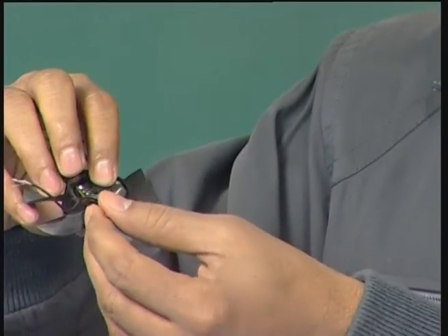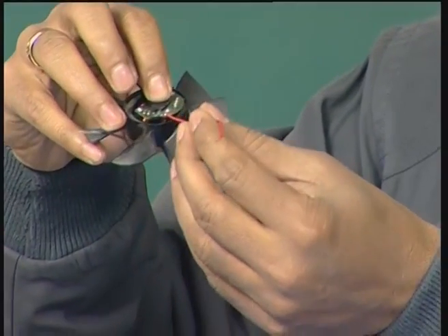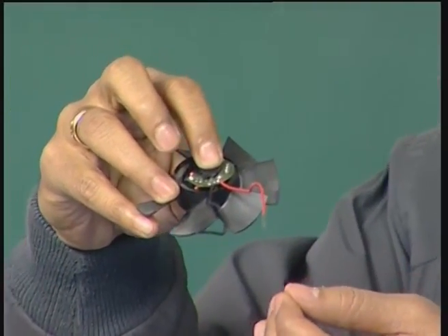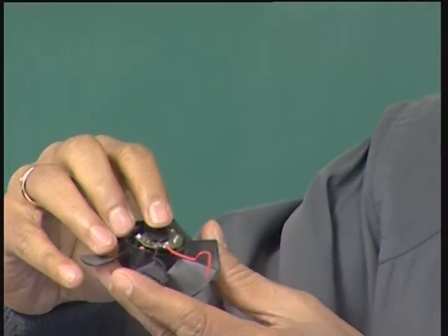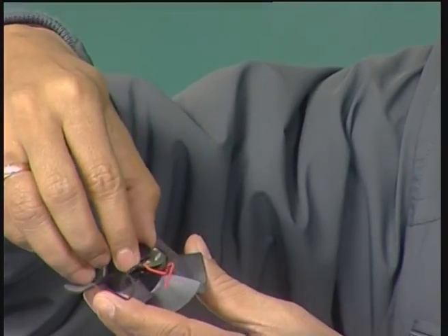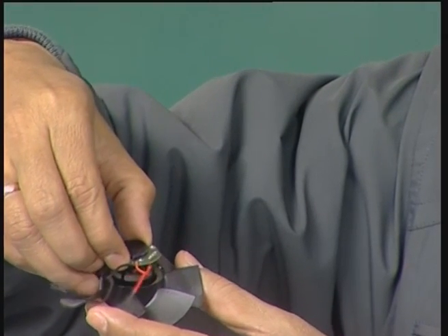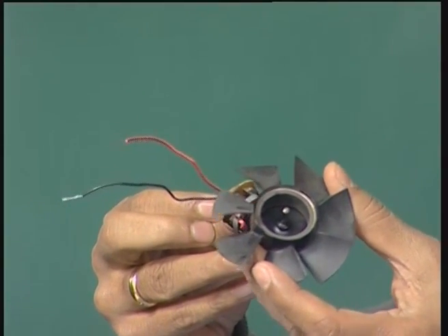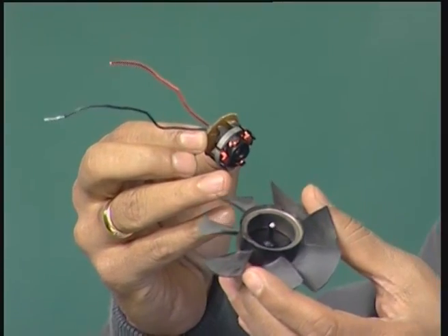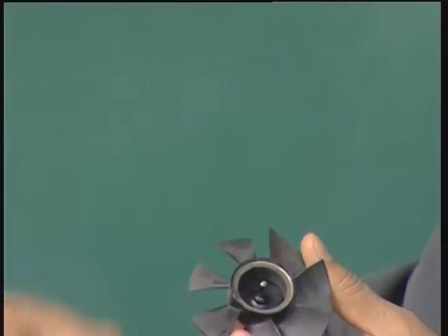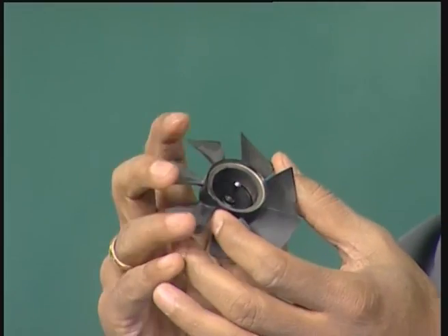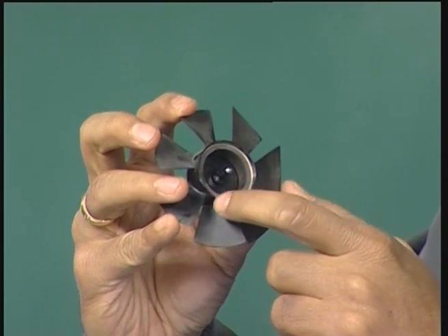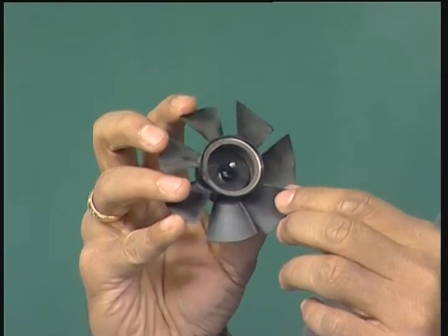These are basically the connectors for connecting the DC power supply, which is plus 12 volt, because in computers we have DC power supply. And if we remove this inside region, we will see that the fan is the rotor. Here the rotor is basically surrounding the stator. So, these are the magnets. The magnets are placed inside this, they are buried here. So, we have south pole, north pole, south pole and north pole inside this, and this is free to rotate.